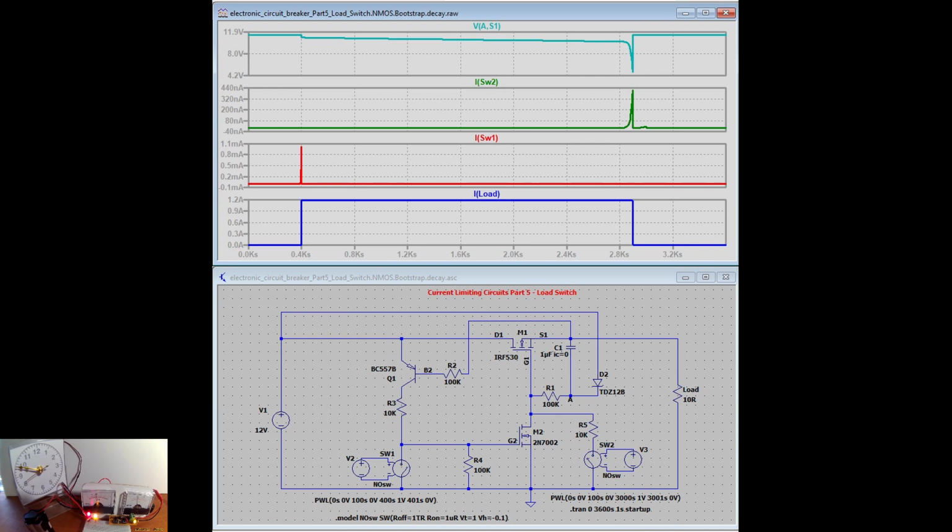4. Many times, especially when used as a workbench load switch, the circuit does not need to stay on for a long period of time. That is when the second switch SW2 is convenient, to shut down the circuit and allow for the capacitor C1 to recharge, cyan line.